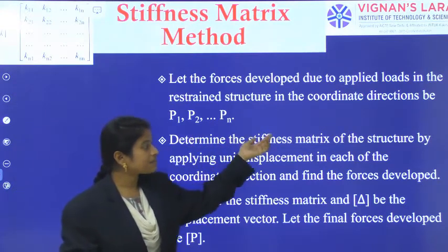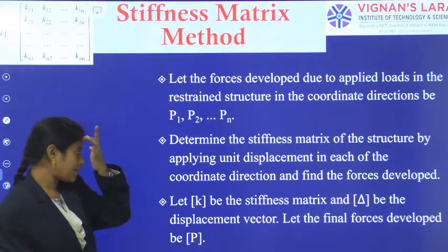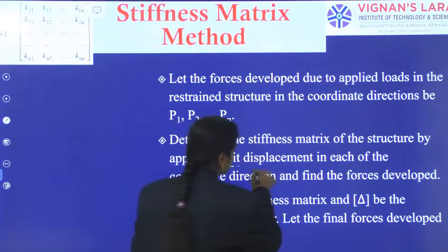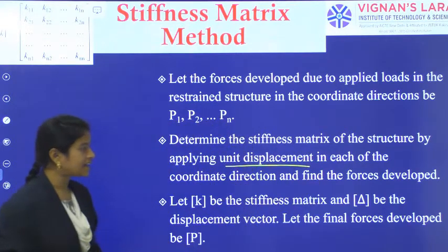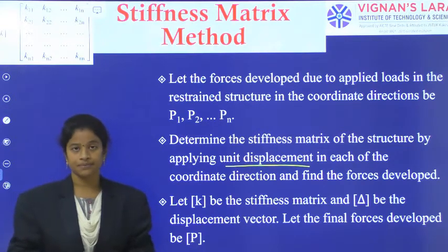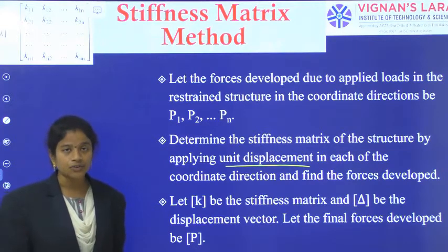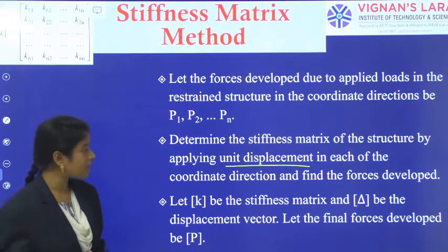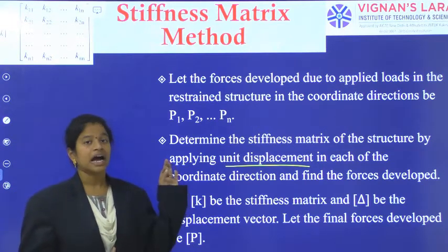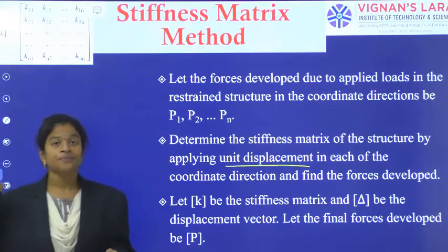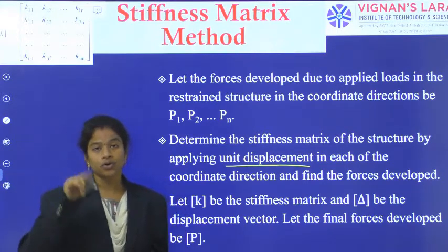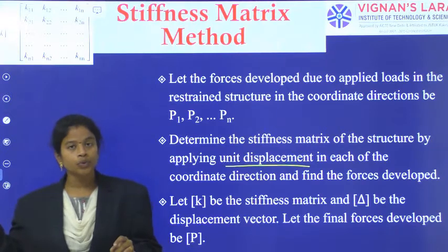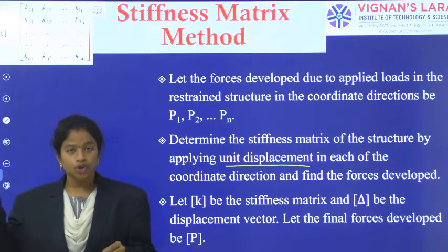Determine the stiffness matrix of the structure by applying unit displacement at each coordinate direction and find the forces developed. So, to determine the stiffness matrix, what should we do? We should apply a unit displacement. There, for the flexibility matrix, we applied unit forces.